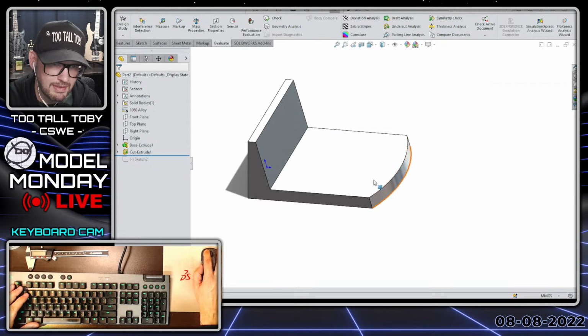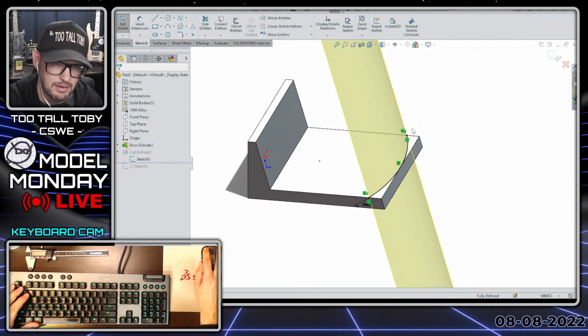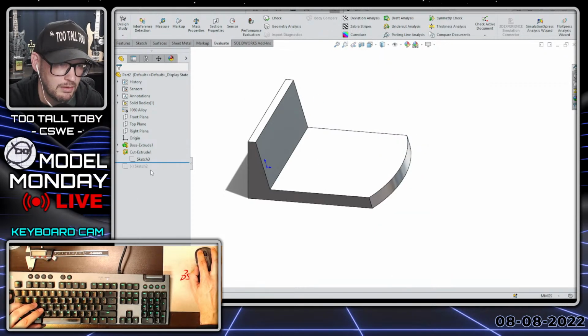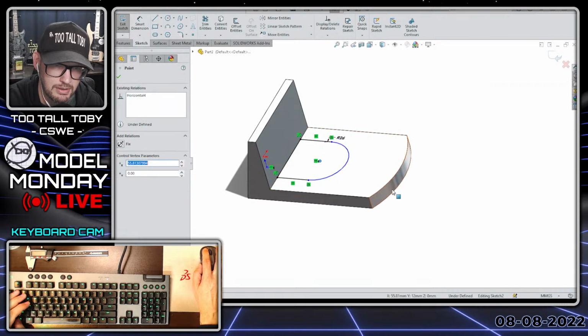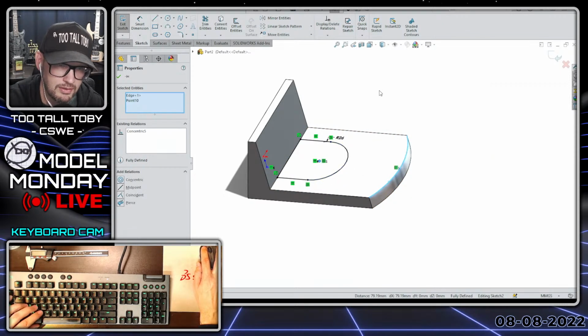Okay, so you only have to make that one arc. That entire sketch just looked like this. I didn't have to create, you know, the extra junk that might stick out on the end there. Just make that one sketch through all both directions, like a surface cut. So now I can roll forward here, and then we have our tombstone, and now we will be able to locate this point or the arc concentric to this arc here.